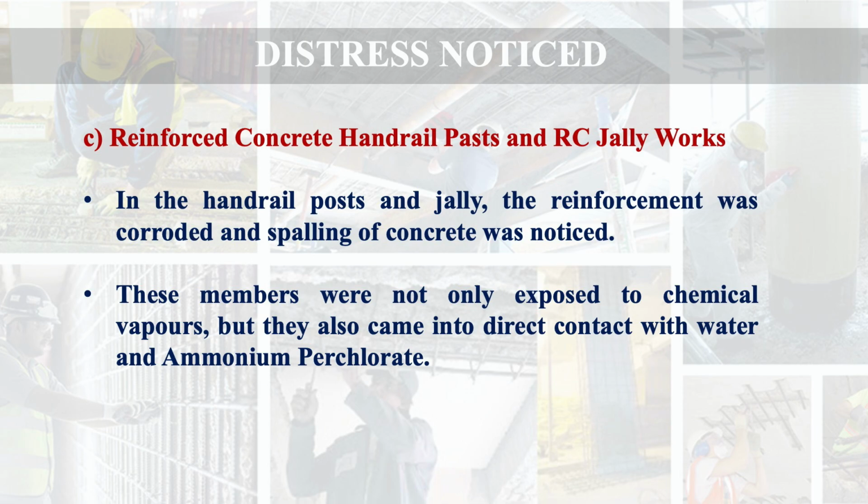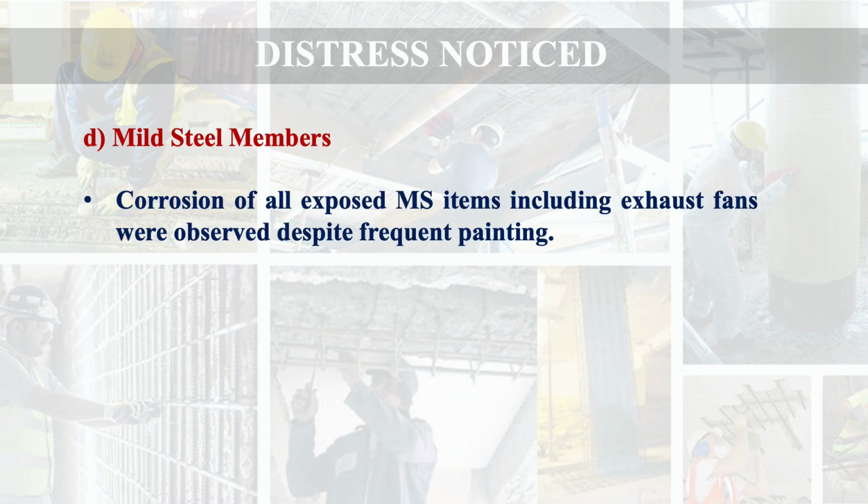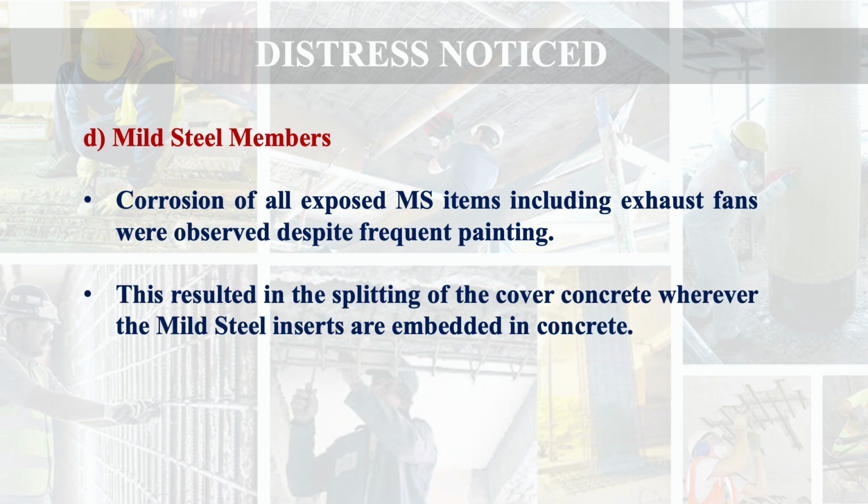Then what happened to mild steel members? In mild steel members, corrosion of all exposed mild steel items, including exhaust fans, was observed despite frequent painting. Means painting also could not protect the items from corrosion. This resulted in the splitting of the cover concrete, where the mild steel inserts are embedded in concrete.